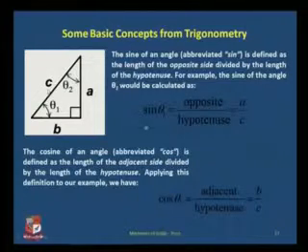Now what is to be looked into here is, when you are solving on your calculator, the most important thing which you all forget is to see whether your calculator is in degree mode or not. Sometimes if your calculator is in radian mode, what goes wrong is that whatever value you get is used by you in degree mode afterwards, which will give you a wrong answer every time. So whenever solving trigonometry examples or solving truss or for MOS, always remember that your calculator is in degree mode only, and only then start solving.